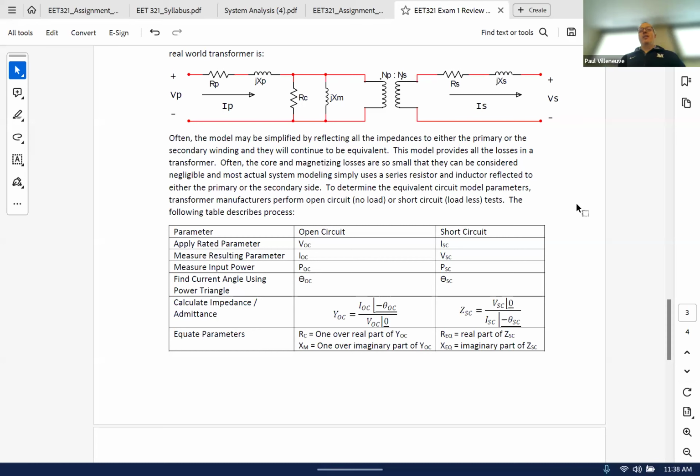Whereas in the short circuit, we do that on the other winding, right? Because we want to put a short circuit. So why not drive the short circuit from the high side, put the power supply on the high side? Because I'm just getting a piece of wire that shorts the terminals. With my power supply, if I have to provide 10,000 amps because I'm on a low voltage winding, that's a lot more expensive endeavor. Anything over like 300 amps, you're probably running multiple parallel cables to make that work, meaning you have to run more than one conductor per phase. I've seen 4 or 5, even some of these wind turbines, they run 6 or 7 conductors in parallel to be able to get the current carrying capacity that they have.